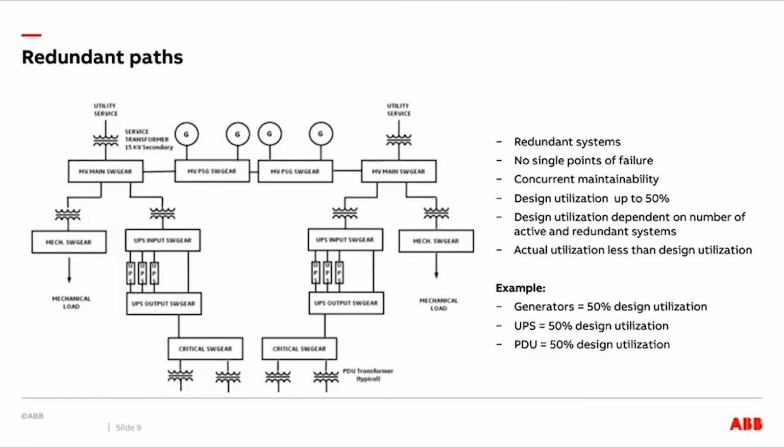Note there are no single points of failure. A failure of any component in the left system does not impede the ability of the right-hand system to supply power to the entire critical load.